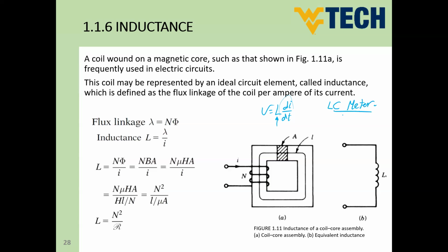So the LC meter, you can connect after creating the inductance. You can connect the LC meter to the two terminals of the inductor, flow the signal of volt and current, and measure the value of the coil inductance and equivalent series resistance. So we measure through this device, we measure L and ESR. ESR is the equivalent series resistance of this inductance. Okay, guys?